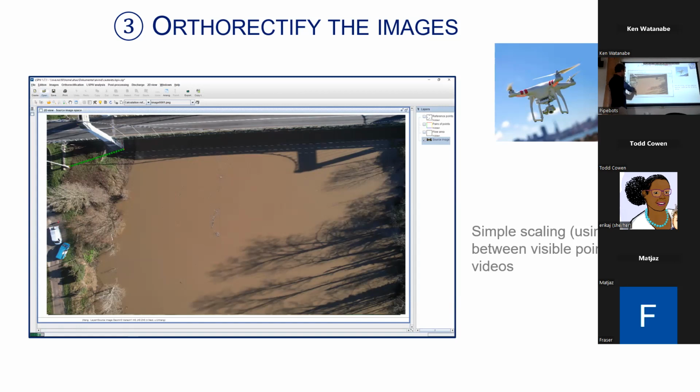So your question was about, I think it's better to have several distances on different orientations just to check that the camera was pointing to the nadir, but take care of picking objects that are in the same plane as the river. It's something to do, also specifying the guidelines like the scaling points. Also checkpoints, to check the scaling. Yeah, that's a good idea.